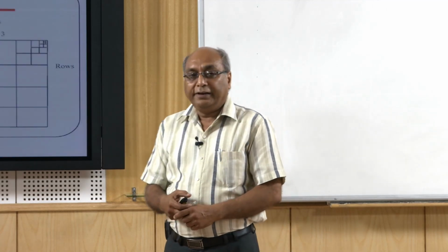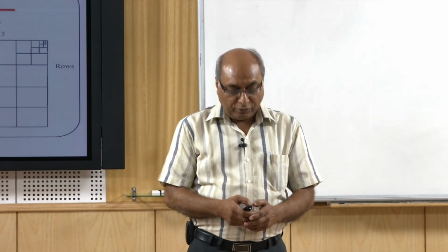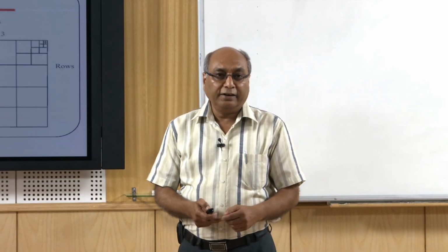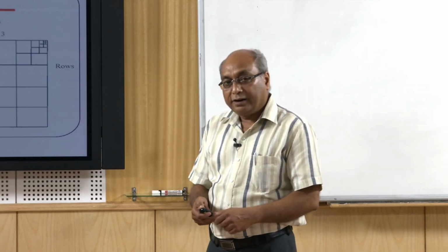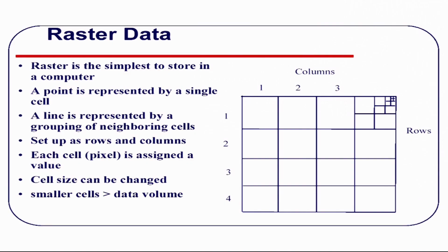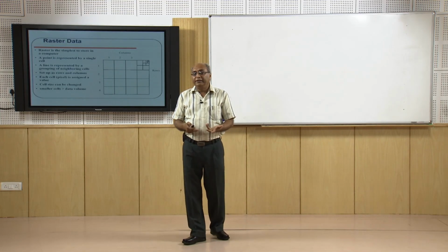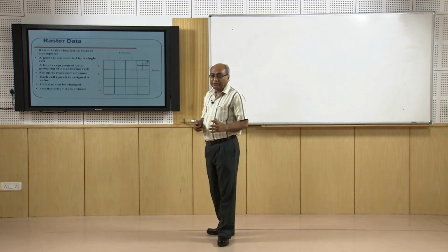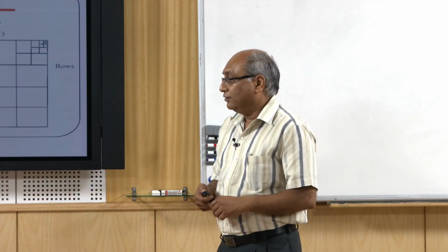As we know, a digital elevation model is a raster representation. It is a surface in grid form, so that each cell represents a value, and as you know, in a raster each cell or pixel can have only one single attribute. Here, if we consider the elevation value, then we call it a digital elevation model, but sometimes people also use the term digital terrain model. Basically it is a mathematical surface which might be created through interpolation, or the digital elevation model might come from remote sensing data analysis as well.